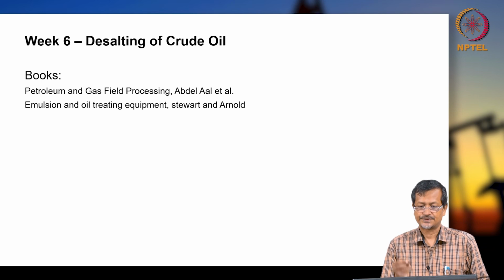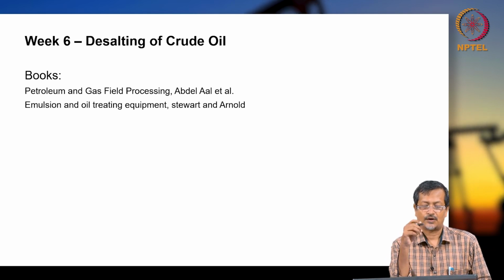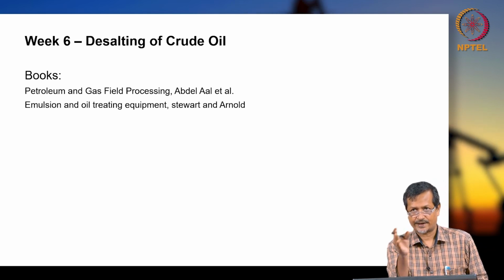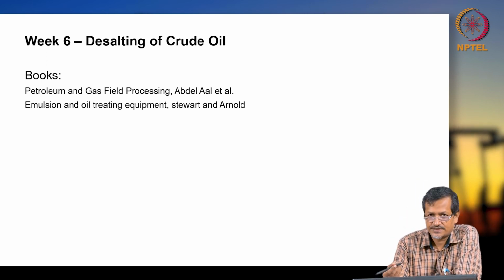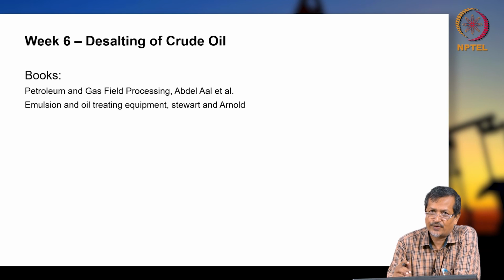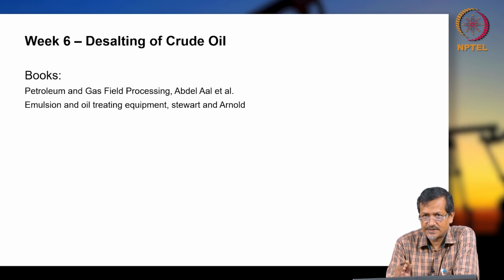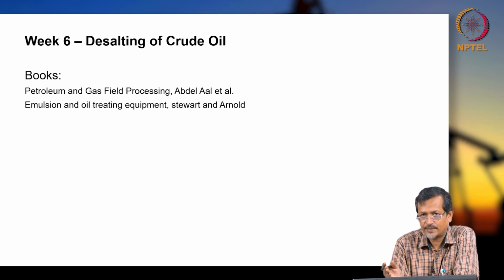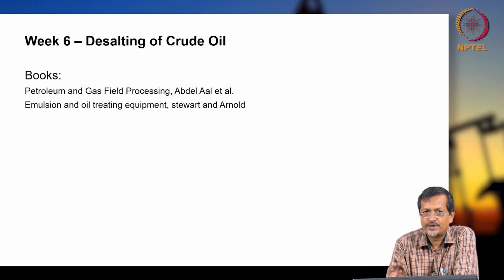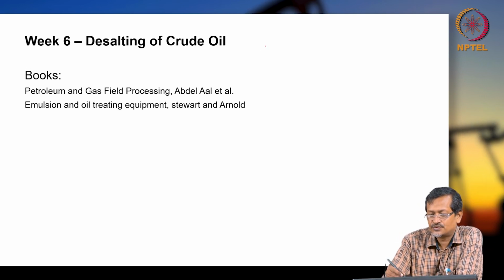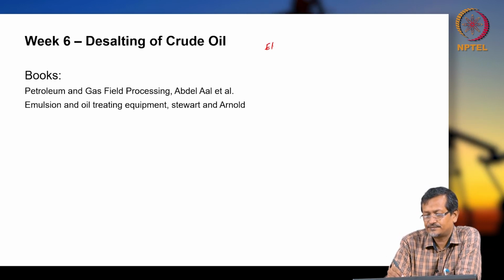So in previous lectures, we have seen how to separate oil, water, gas. There are vertical separators, horizontal separators, spherical separators. Then we have seen there are emulsion treaters where we add chemicals, we add electrodes to remove water particles, and we heat to change viscosity. So electrostatic treater,